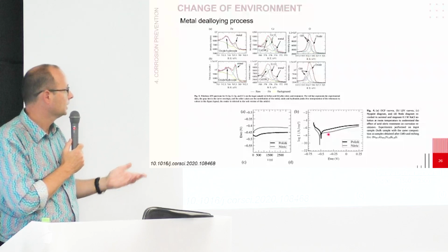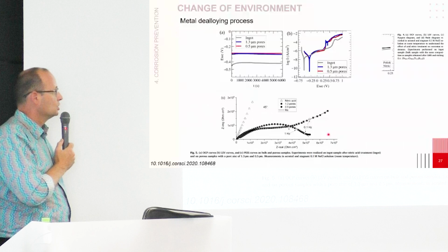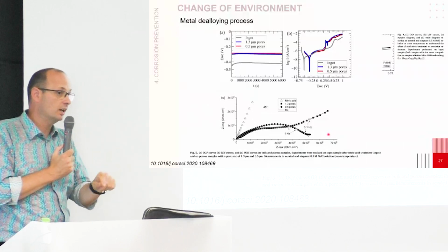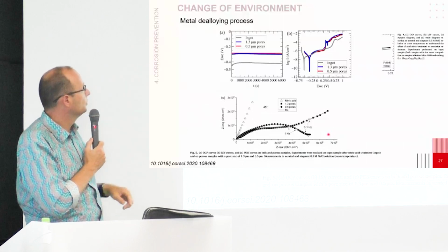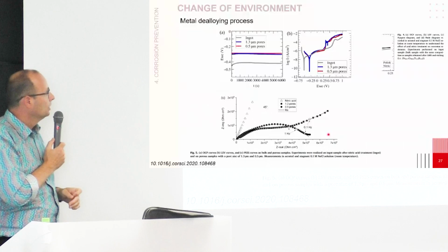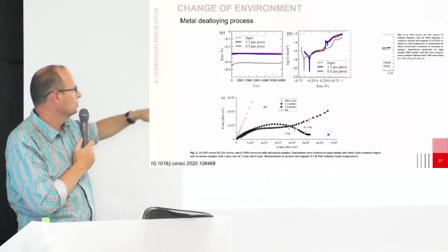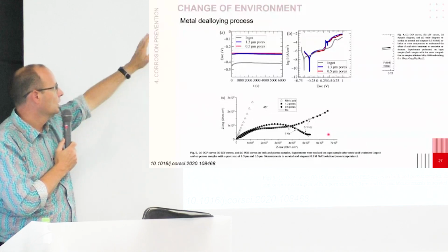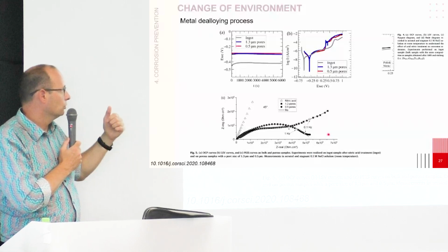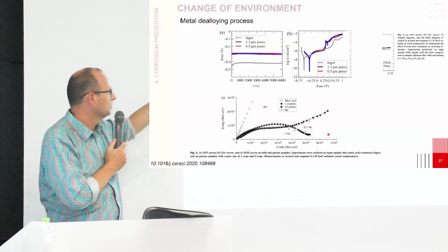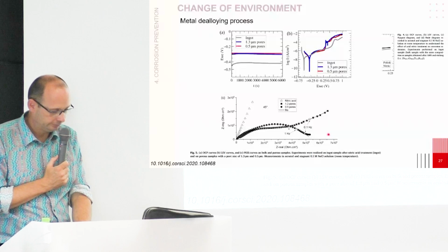So this is because you are changing the surface of the material. So the environment is changing the surface of the material. Unfortunately, in this case, the environment is sodium chloride for the final use, and because you have a porous structure, even if you are trying to reinforce the surface of the material with a passive film, it doesn't work. The film remains quite sensitive to degradation.